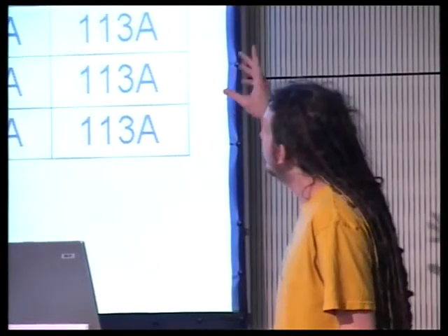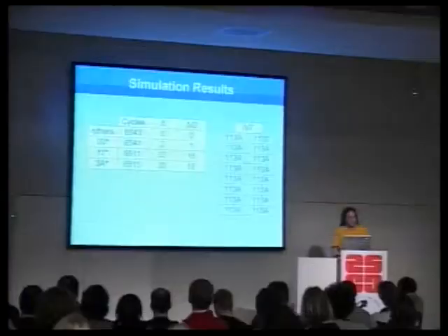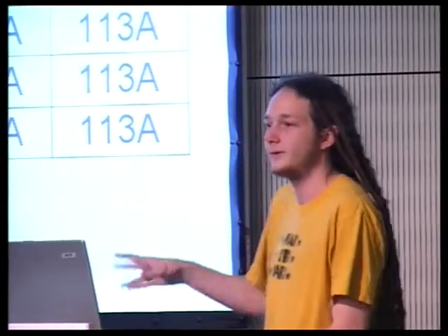So in this case, by using the interrupt vector table, every complicated firmware image will automatically have its own sort of unique password. And the manufacturer will have a copy of that password, but no one else will. And the compiler can't not set the password. So when you have all of these fly-by-night, hey, let's make an msp430 compiler companies, they all, by the very nature of the chip, have to make a unique password for each image.